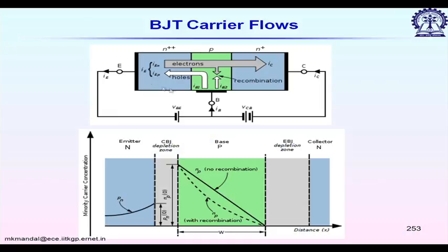Now, looking back to the basic operation of a BJT, I'll skip the very basic things, and only discuss the limitation which arises at higher frequencies. Let us consider one NPN type BJT. Usually NPN type BJT is popular at higher frequencies, since it involves mostly electrons and electron mobility is higher compared to hole mobility.